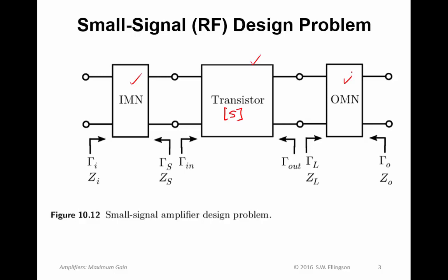In other applications and in future lectures, we will have other goals or other combinations of goals which will lead to different impedances. In any event, here I'm reminding you about the nomenclature that we use. For example, Zin will typically be 50 ohms. It will be in this design problem, and it is in many RF problems, but it could be something different, and the techniques will still work. But here it's 50 ohms. Zout is 50 ohms. I use the subscript O here to distinguish it from another place where we're interested in the output. So just to be clear about that.